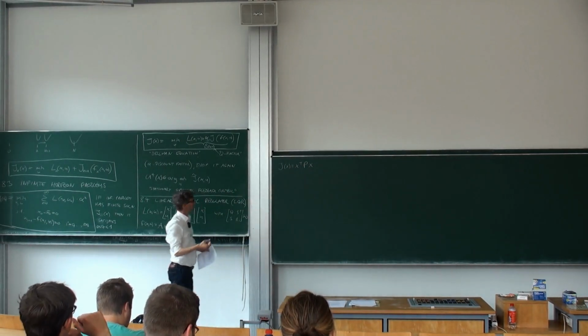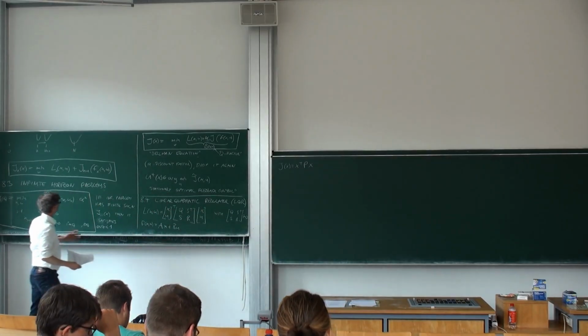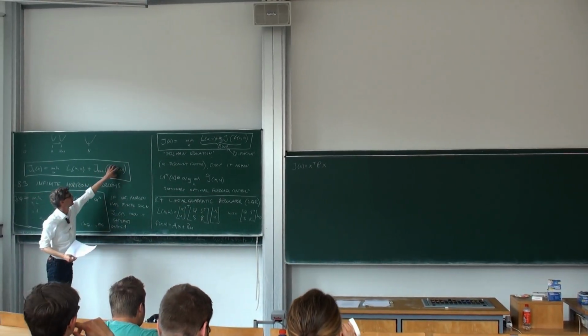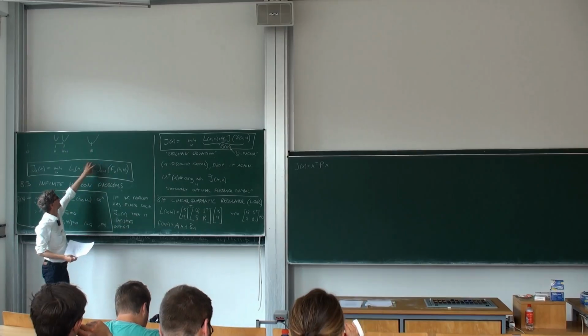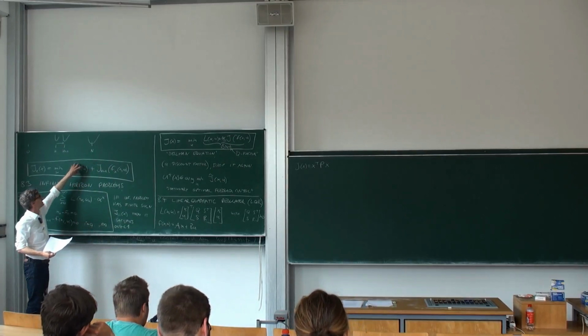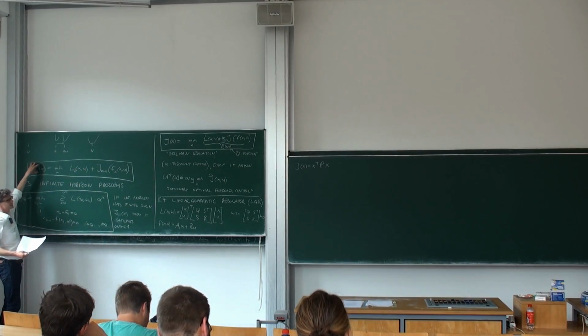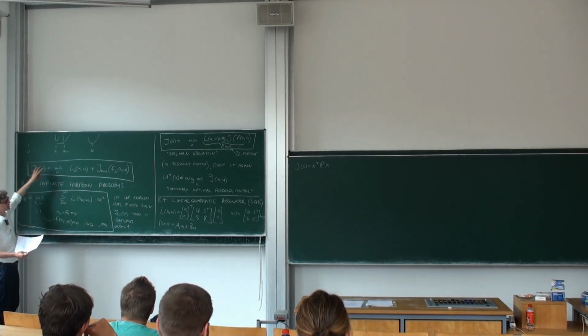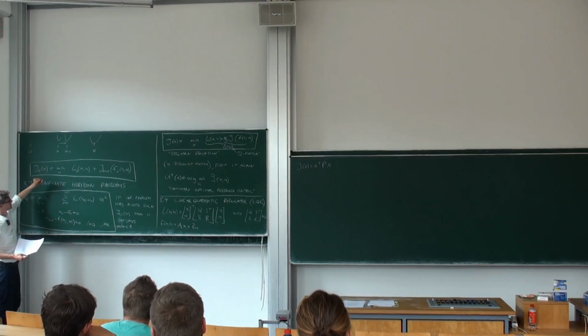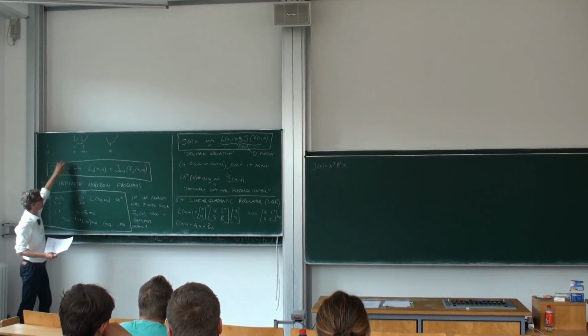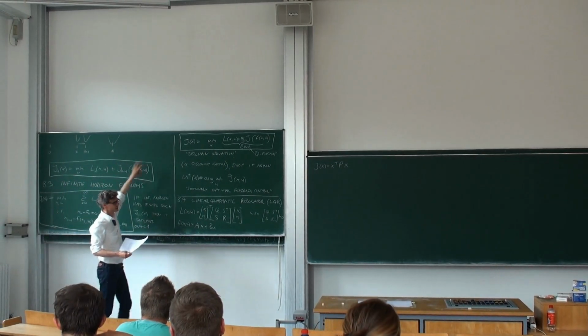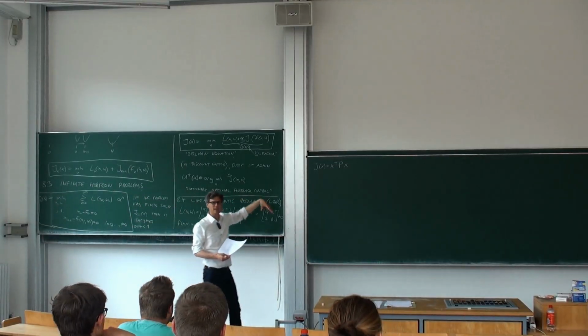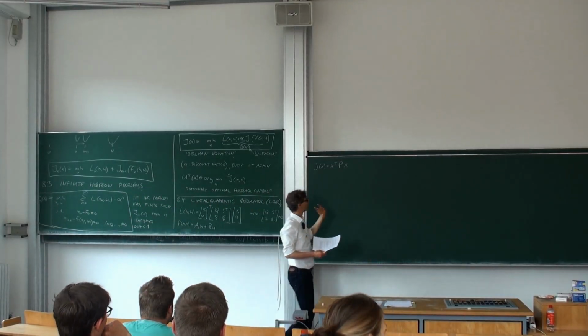If the system is linear, the cost is quadratic, and this cost is also quadratic, then the minimizer also leads to another quadratic. We derived the recursion that the matrices P would satisfy. If the J here and the J here should be equal, we just need to drop the index on the P in the previous equation, which we can copy.